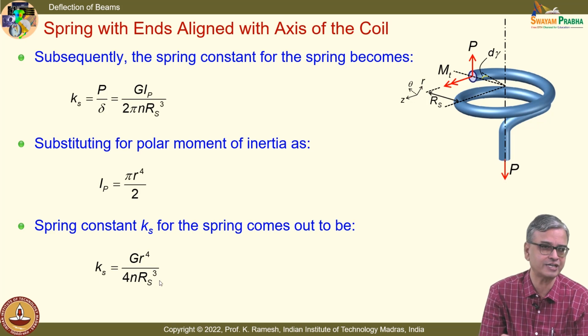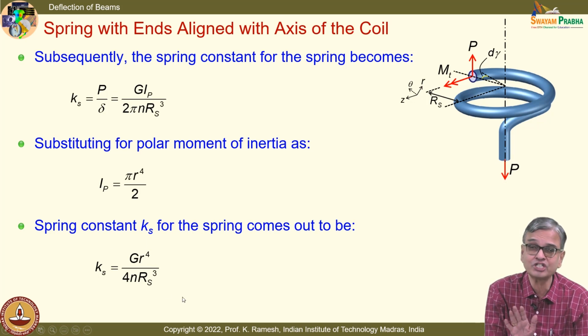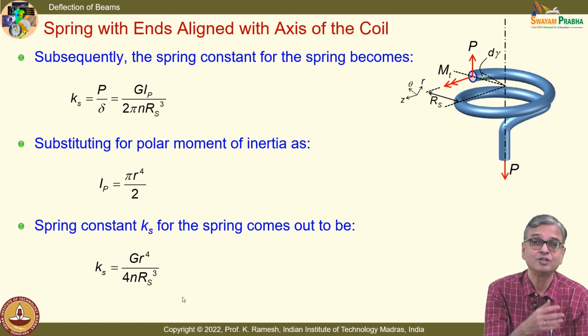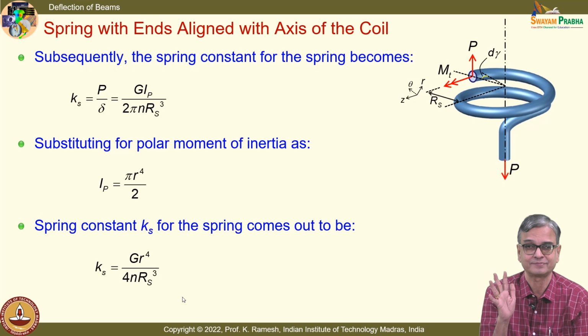There are different considerations. So in contrast to shaft design, you use alloy steel and you don't use the conventional tension test for getting the properties. So you utilize the advantage of what happens in a small wire compared to a bulk material. You handle it this way from an engineering approach. Fine.